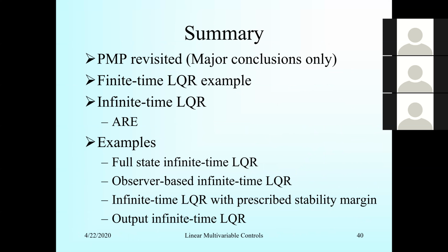So today we basically covered quite a lot of things. Talking about ARE, talking about observer-based design. We went through an example. Full state feedback, and we talked about how you can use an observer. We talked about ARE and prescribed stability margin. Yes, we can also do output feedback using an observer. But the warning is that using LQR plus observer, you will have the issue of loss of robustness.